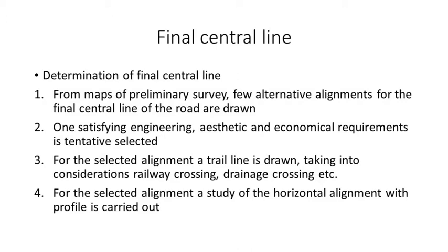In the ground reconnaissance survey, we have to find out the information of valleys, ponds, lakes, marshy land, hills, some permanent structures and other obstructions. Okay. Next, what is the value of gradient? What is the length of gradient? What is the radius of curve? That is also required. Next, what is the number of cross drainage structures, and the type of cross drainage structures?